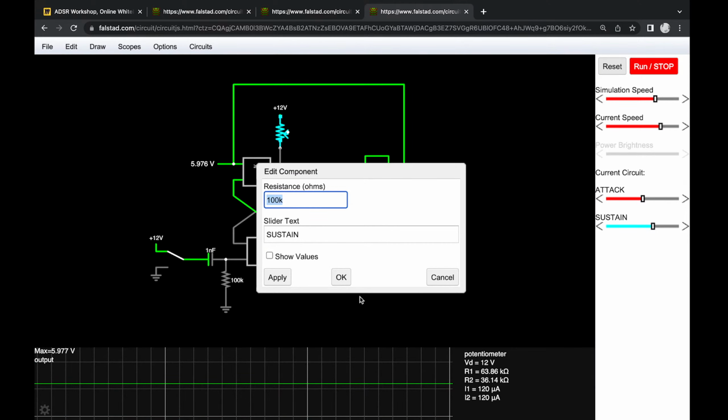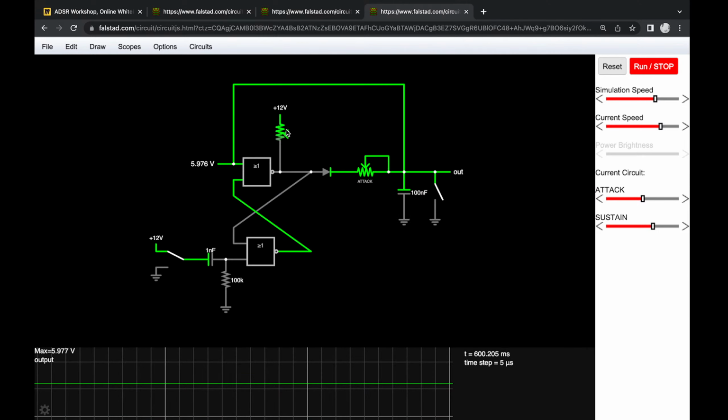This is 100K resistance, and if we want to discharge to this voltage level, right now it's 4.3 volts, then we're going to need to buffer this. Because we need the current to flow out of the cap and then be sunk by something. And this potentiometer is a resistance, and so it can't really effectively sink voltage properly.